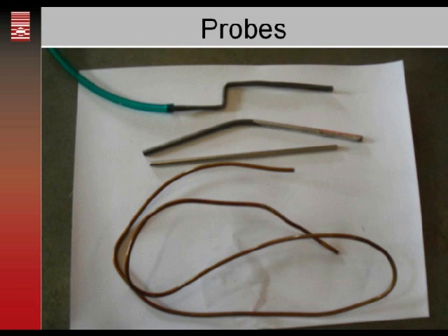Brake line tubes come in 2 diameters. One is a little bit bigger than 1/8 inch. One is a little bit smaller. Either one works fine. The smaller one is easier to bend and make sharp turns with, to get under doors, or bend to get around tight angles.